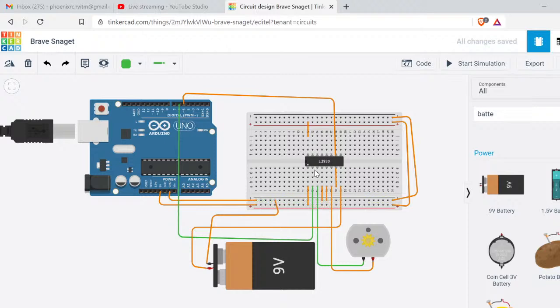Yeah, because we have to connect internally to ground, and it is done in the motor driver internally, but we are using a microcontroller, so this is the way we have to control. If you use a board, you can just plug in using jumper wires, but here I'm explaining how you can use separate ICs also.